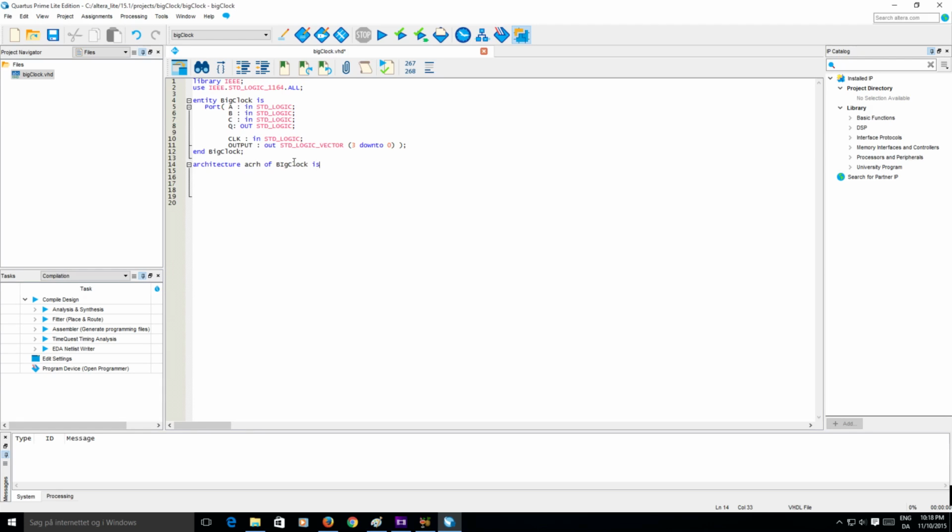And if we want to define any signals, we can do that here. They will be local to the architecture and cannot be seen outside the block. The port I/O that we define up here can only be an input if it's set to an input, and only an output if it's set to an output. That can never be changed. You can define them as in-out or buffers, but that can get really messy really fast, so only do that if you have to.